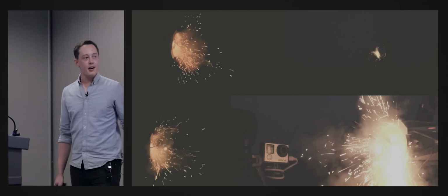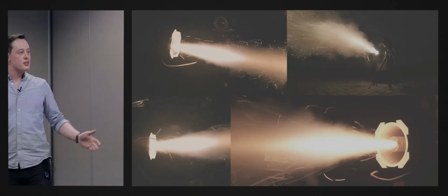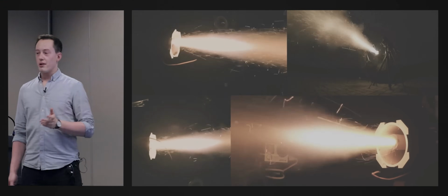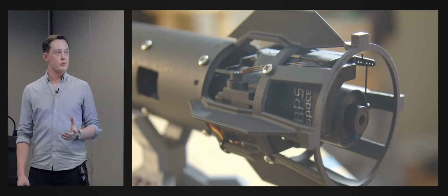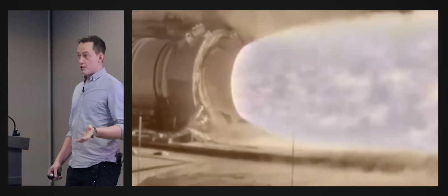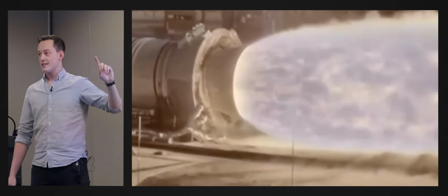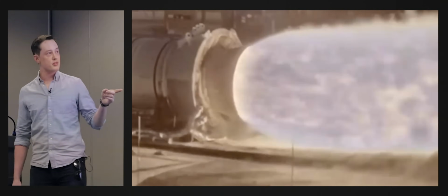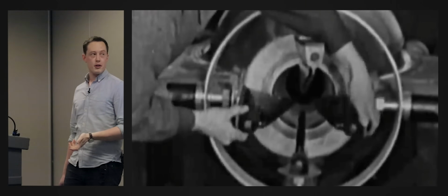So how do you do it? How do you accomplish TVC in any scale? What I like to do is gimbaling the motor, and by that, you put the motor on a dual axis hinge. So the motor can hinge to the side, it can hinge up or down, and by that, you change the vector of the thrust. But you can also do it with the nozzle of the motor. This is the Space Shuttle SRB, solid rocket booster, and this is some sped up footage of it vectoring the nozzle during a ground test.